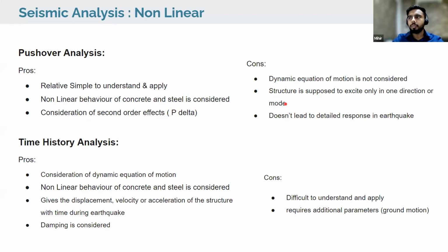Like we usually apply pushover in the X or Y direction, or you can apply it for the dependent mode that is occurring. And similarly for the time history, we have the nonlinear properties, and we also have the damping, and the dynamic equation of motion is considered.